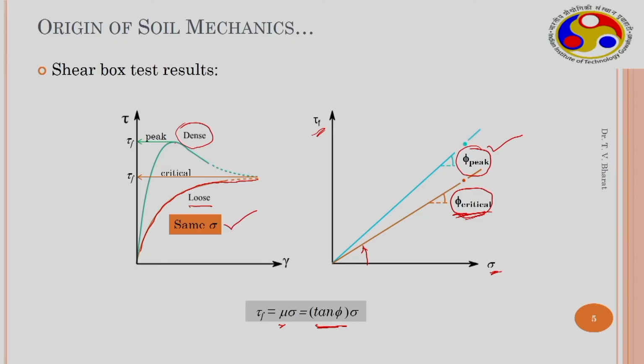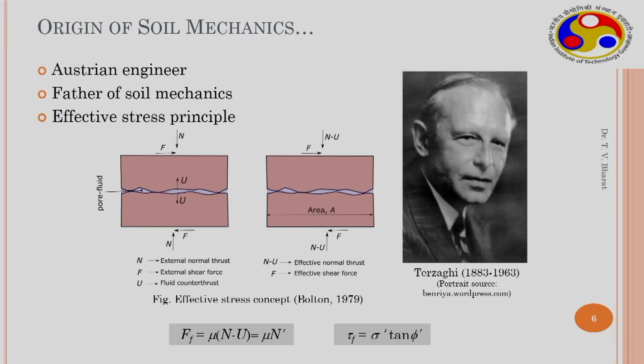However, here you have a two-phase system. You have soil solids and air in the pore space. Then comes the effective stress principle, where in case you have a pore fluid in the pore space of the system, when you apply normal force and frictional force, there is a counter thrust that is acting from the pore fluid. So therefore, this is the force that is acting at equilibrium, and this is the force acting at the equilibrium. This is given by Terzaghi,